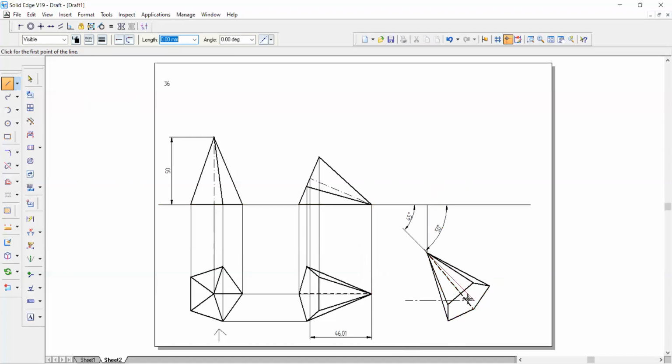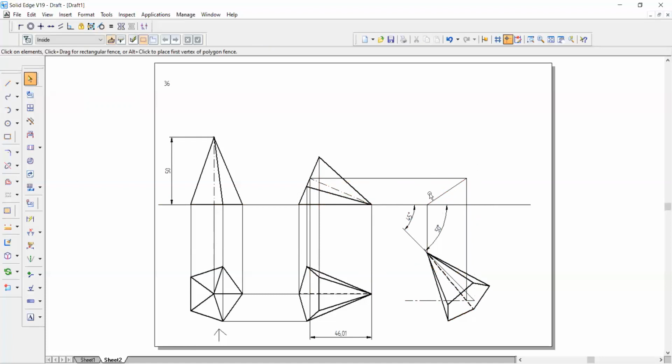Okay. Again, O1, if you want to project, just project till the intersection. From the intersection, I know O1 is somewhere here. Join this. So from here to here is your axis line. Just draw this. Change this to axis line. Change the thickness of the line to 0.35. Okay. Then the rest of the other things.